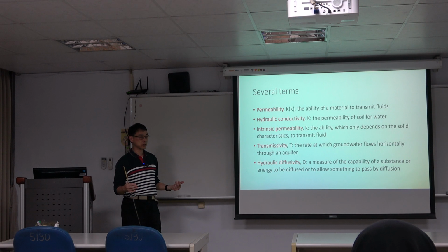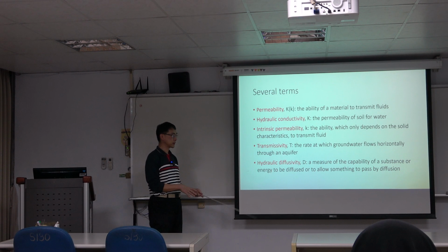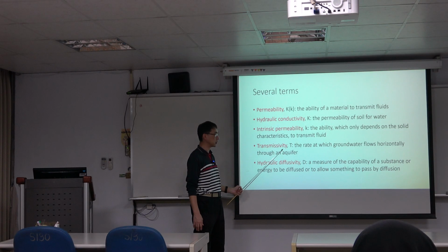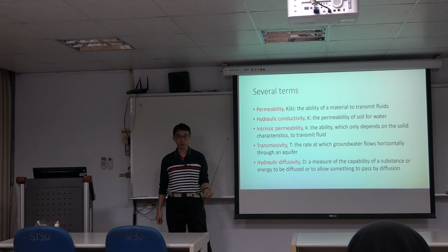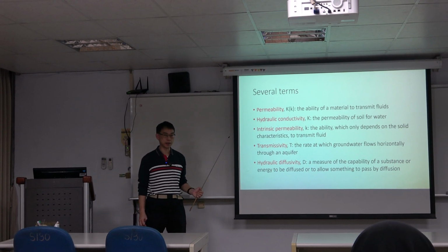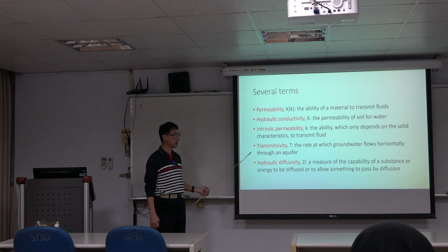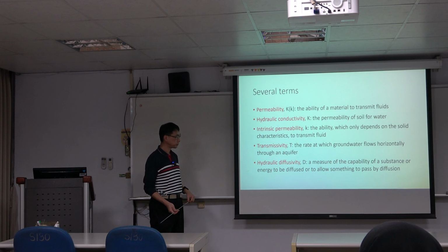But for the ideal case, if we have fully penetrating wells, we are able to gather only horizontal flow patterns. So commonly, under the assumption of horizontal movement, we are able to use the pumping test to quantify the transmissivity using the Theis solution like that.